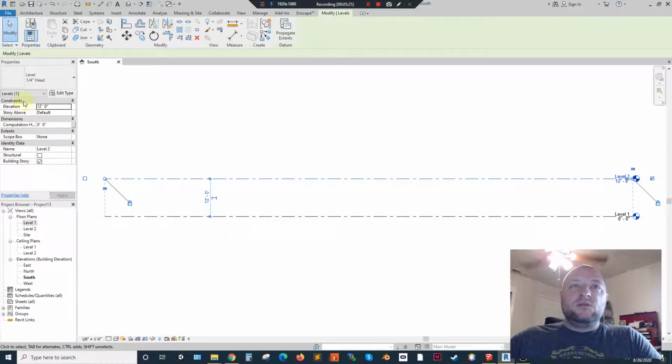Now, whenever you interact with this properties box, make sure that you don't move the mouse outside. See this apply button right here? Watch what happens when I start typing here. I'm going to click right here, and it gives me the option to start typing. What students will sometimes do is move the mouse out here. As I did that, the view changed back to this window and that apply option went away. So when you're working with this, make sure that you don't move your mouse outside of there. It's kind of annoying.